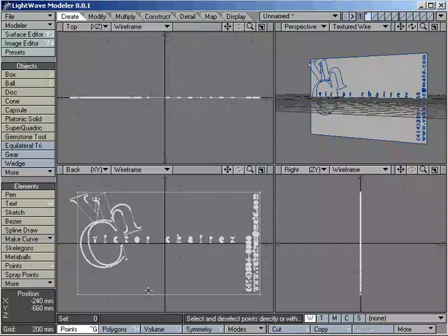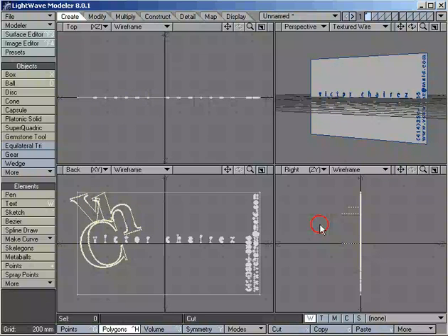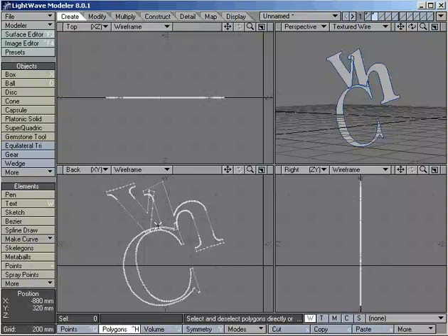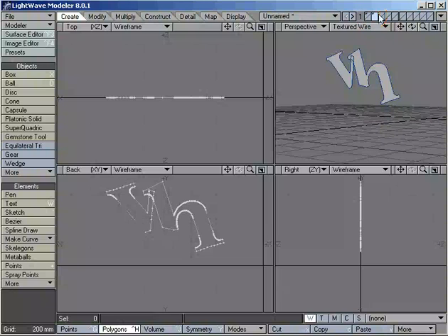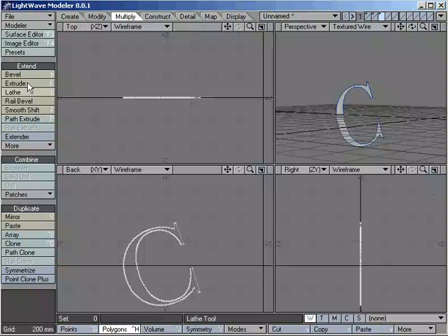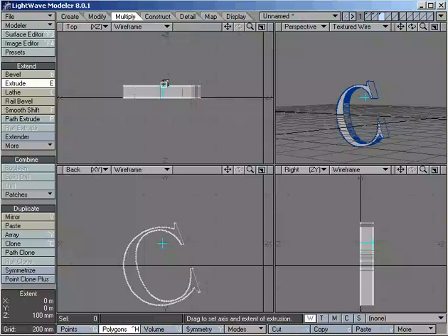So what you would do in Lightwave, once this is brought in, let's say this is just the logo, I'm going to switch to Polygon Mode, and I can select these, cut and paste. And I still have probably more than I want to deal with. I might want to actually break these into 3 separate layers. In fact, let's do at least one of them. I'm going to cut and paste. Once I have that, I can treat it just like I had done it originally.